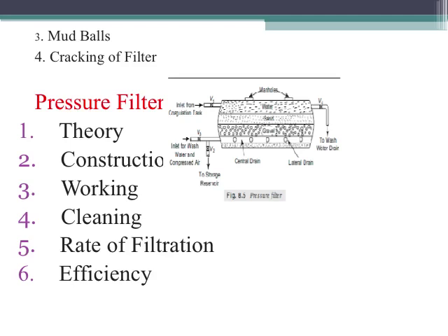In fact, this acts like an additive which starts becoming a clogging particle. During inadequate washing of the filter, this mud may sink down into the sand bed, and then sticks to the sand grains and other arrested impurities on the grains, which forms conglomerations of mud balls, that is, from the turbidity and the flocs.